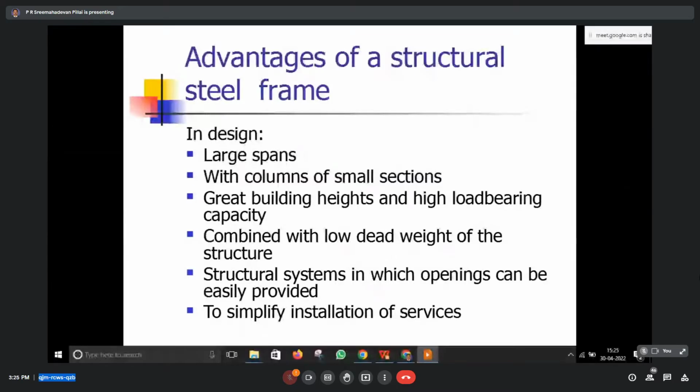See, these are some of the advantages when steel structures come in. Not only that, in most places the sections of concrete can be highly reduced by properly positioning steel elements. Even in many tall buildings, we have what are called core reinforced columns, where concrete is reinforced at the core with heavy steel sections, not like square or circular bars. They will have steel sections inside in tall buildings.